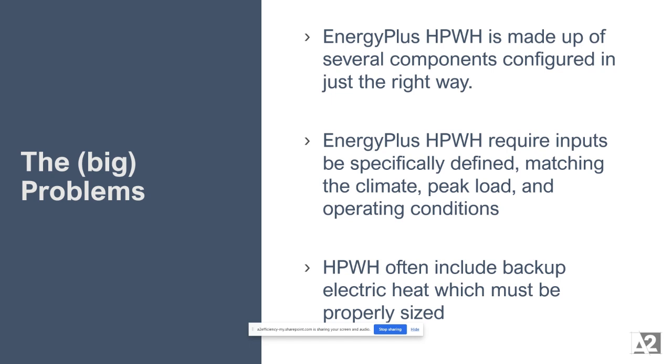Where is it in the building? Is it pulling room air? Is it pulling outside air? And then often the whole system includes a backup heating device sometimes, or an additional electric heating device, and that also needs to be sized.